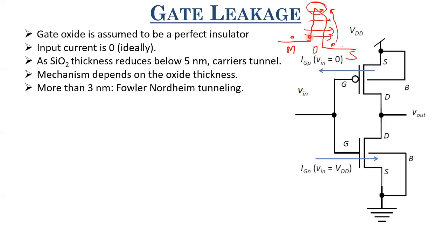So only the highly energetic electrons which are here can tunnel through this small barrier here, right? The barrier thickness here is pretty small, since the electric field is applied, so the energy bands are bent like this. The barrier is effectively thin here at the top, and it increases and then remains constant throughout. Since the barrier thickness is small at the top, energetic electrons present here can tunnel. This is what happens in Fowler-Nordheim tunneling. It's tunneling through a triangular potential barrier.